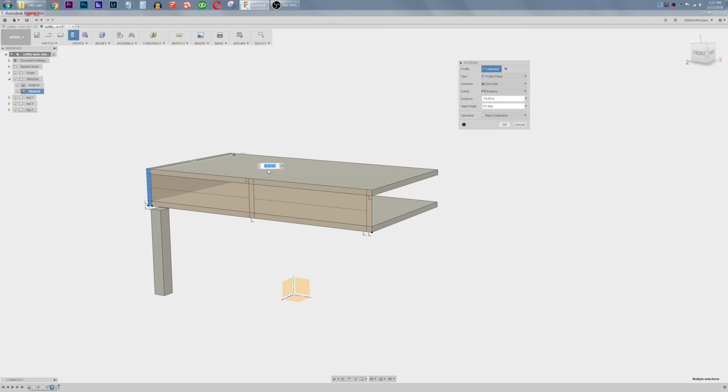So if I just, for example, type in 19 and leave it there, and then change the footprint, my width on my footprint, which establishes this size, to 14, then these are based upon that footprint sketch. It's going to update the 14. This one's based upon the number that I put in. It's going to stay at 19. I want this to update as well.